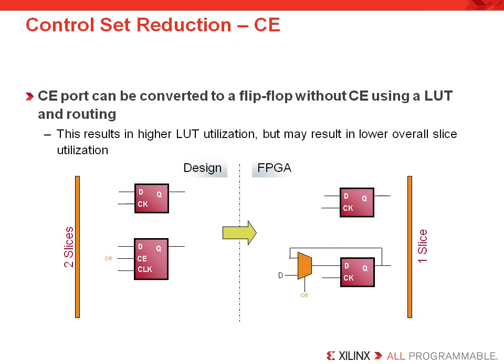So here we see an example on the left where the designer has built 2 different types of flip-flops, one with the clock enable, one without. By allowing the synthesis tool to move that clock enable to a LUT input, effectively, as you can see in the right portion of the slide, that now that clock enable gets sucked up into a LUT input, as well as the current status or the D port gets fitted in as a LUT input.